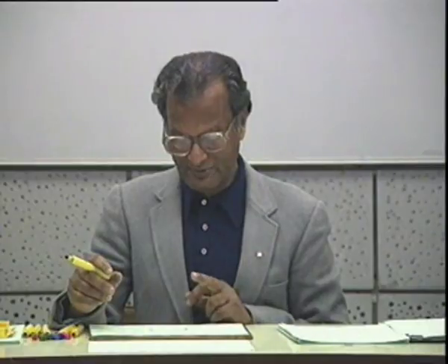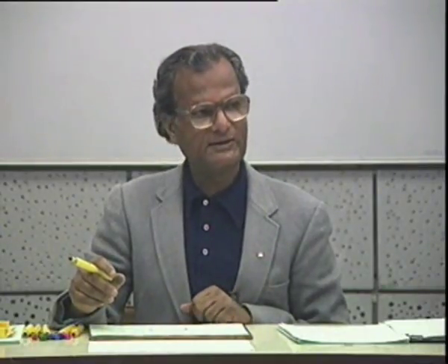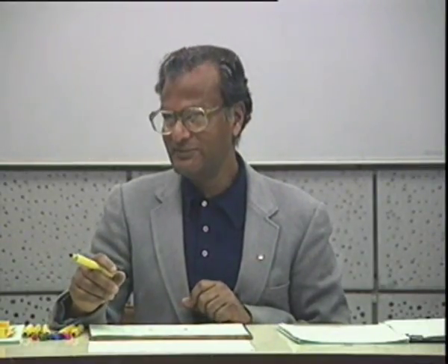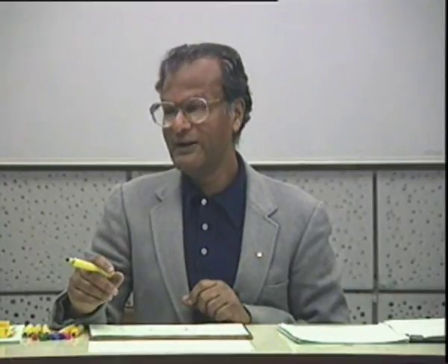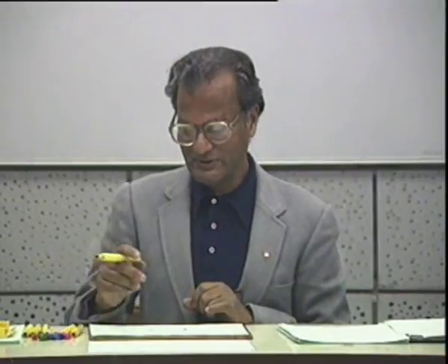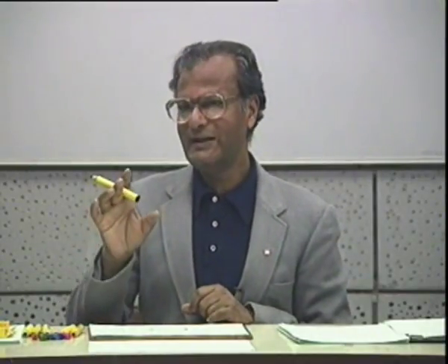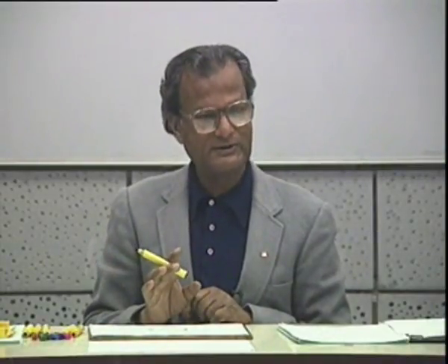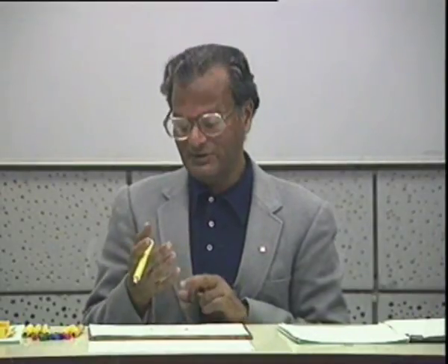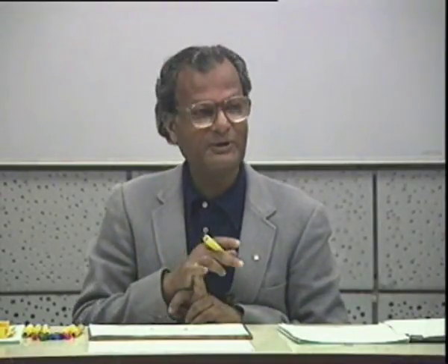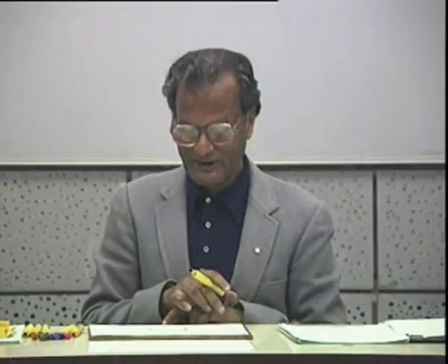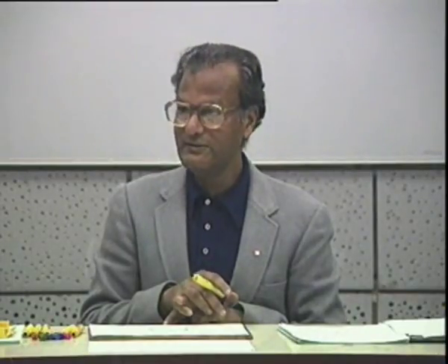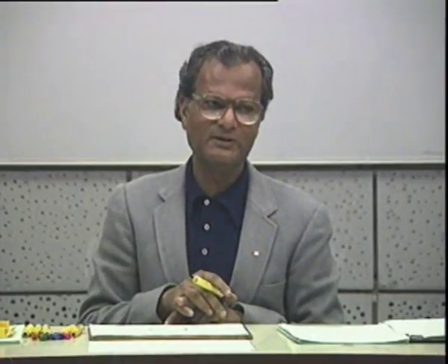As I said, JFET could be either P channel or N channel, but however N channel is preferred because of the higher mobility of electrons as compared to holes. So we will mainly, just like BJTs, we are taking NPN as the basic material. It's not that PNPs are not used. For example, in a complementary symmetry, you require an NPN and also a PNP. Now, in JFETs, N channel devices are preferred because of the higher mobility of electrons.